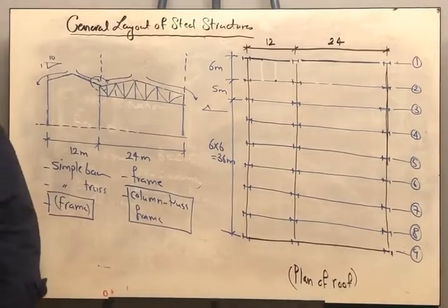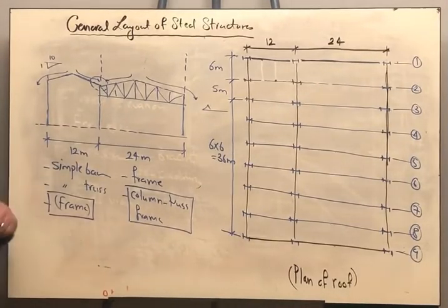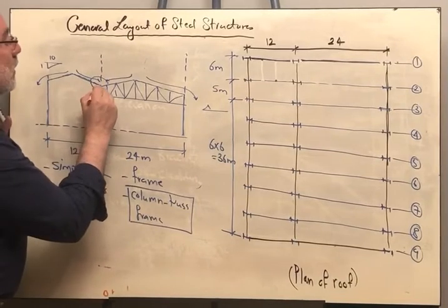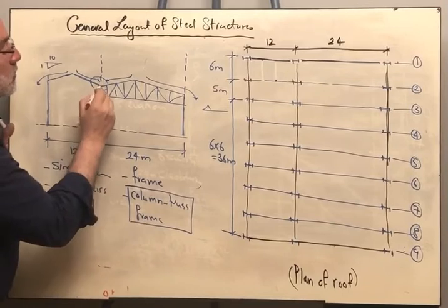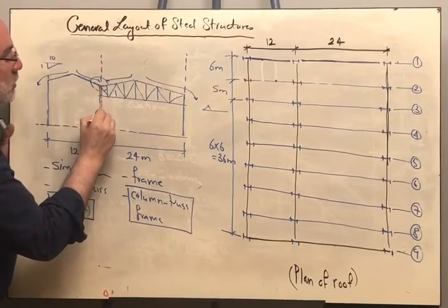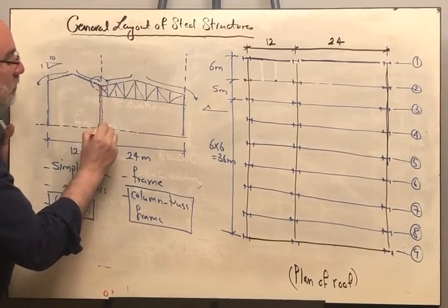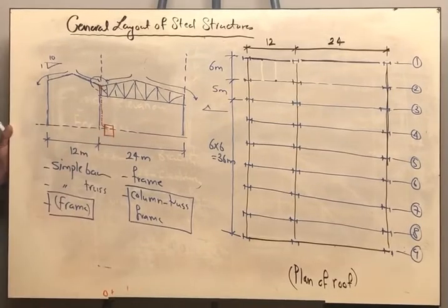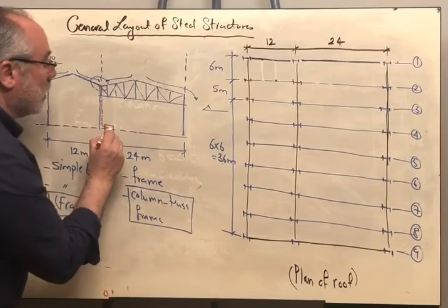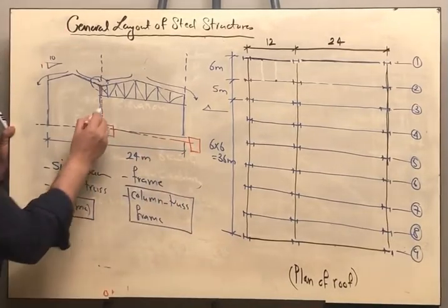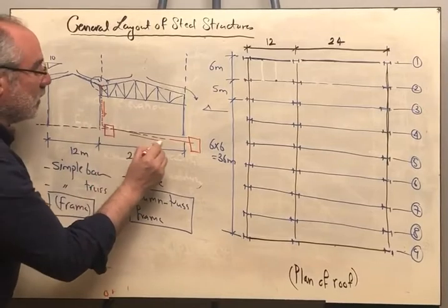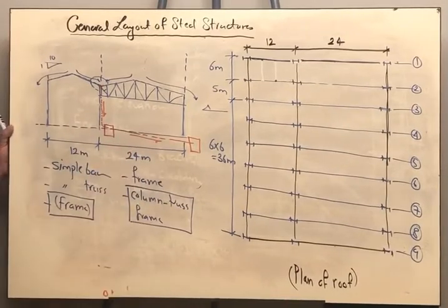Therefore, we should provide a rain gutter or something that will collect the water, and then it is attached to a pipe, and this pipe or downspout is attached to a chamber where we collect the water, and then we are draining it to the outside of the structure like that. So water will be drained in this direction and then under the ground in that direction.